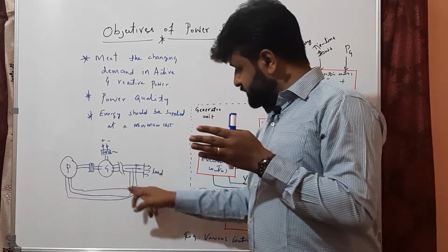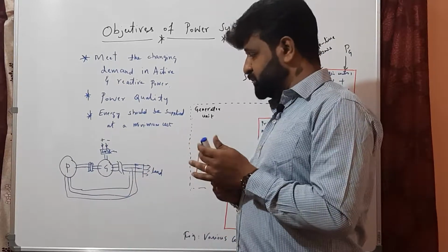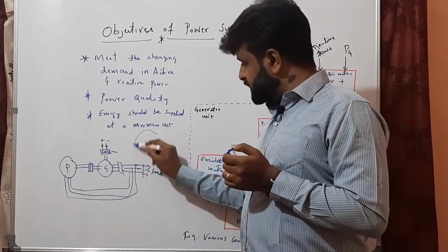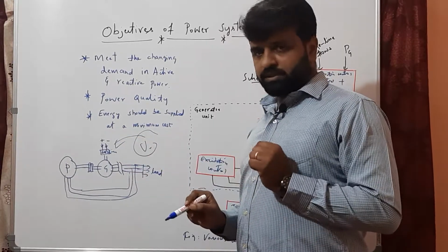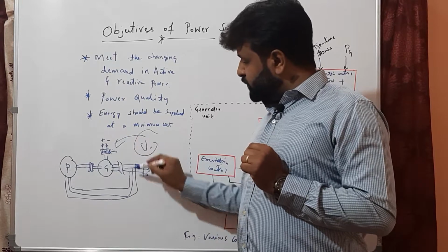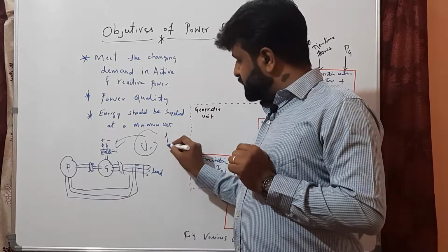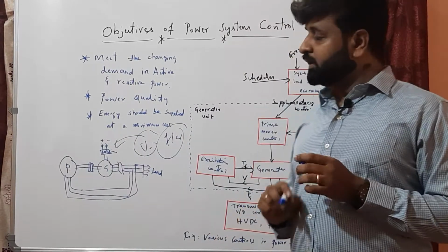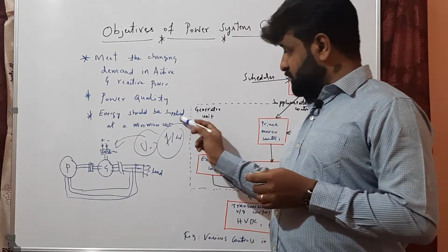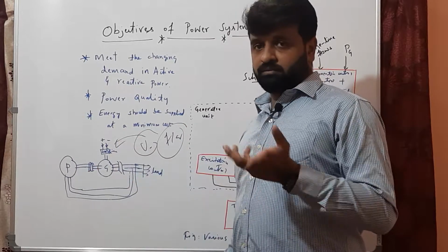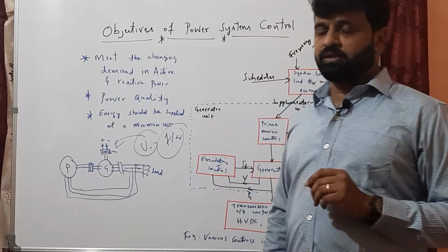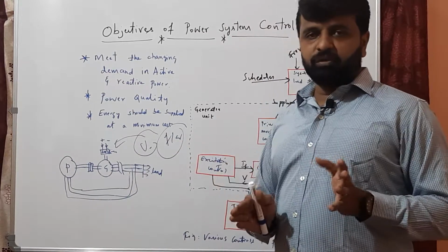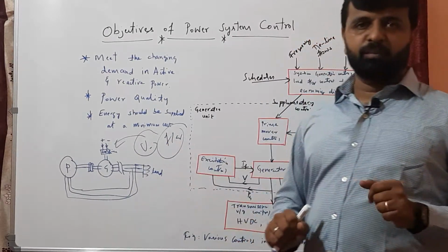Any variation in the transmission line voltage, for example, will affect the generators, so it is controlled through the excitation system. And suppose a frequency variation happens, it will affect the prime movers. If there is more variation of frequency, it will affect the turbine coupling, so we may get damage. That is the reason we should carefully control these parameters.